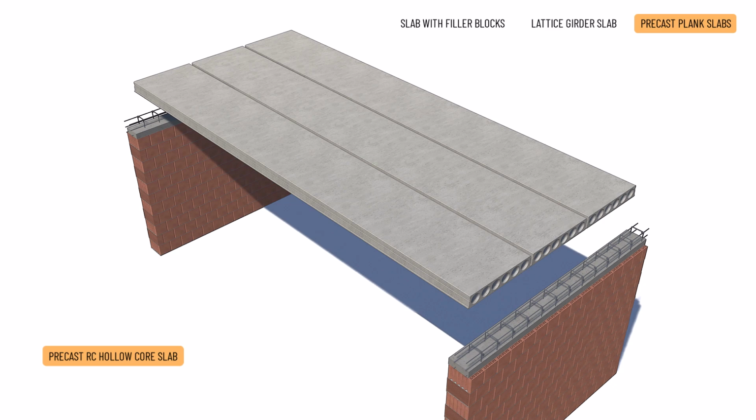The larger span is associated with a very high structural height, from 20 centimeters to 50 centimeters, in addition to the typical width of 120 centimeters. As these are custom-made products, it is necessary to calculate reinforcement to ensure the necessary load-bearing capacity. Another advantage of reinforced concrete hollow core slabs is that they usually do not require any top monolithic reinforced concrete layer. The hollow cores are necessary to reduce dead load and are suitable for mechanical ducting.